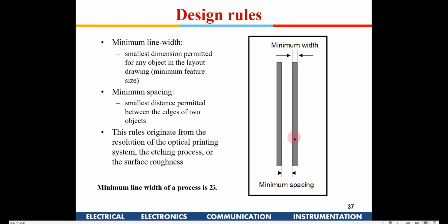So all your VDD rail and ground rail, you should make pretty thick, because high currents will flow through those rails. And there is also a minimum spacing rule. When we are running two metals, of different layers like metal 1 and metal 2, they can run parallel to each other because there is an insulator, so it doesn't matter.